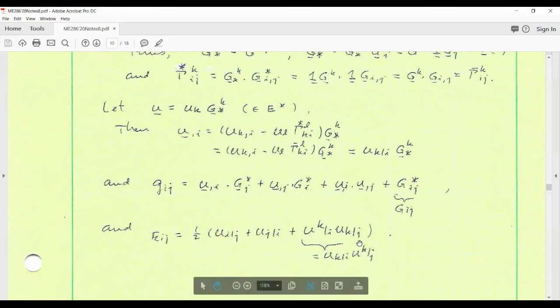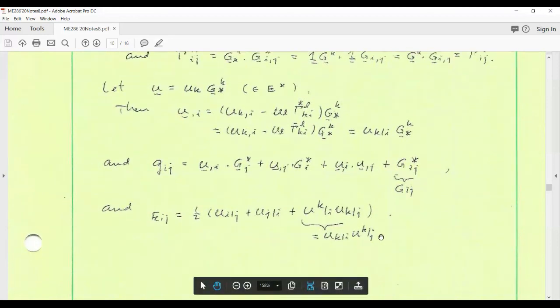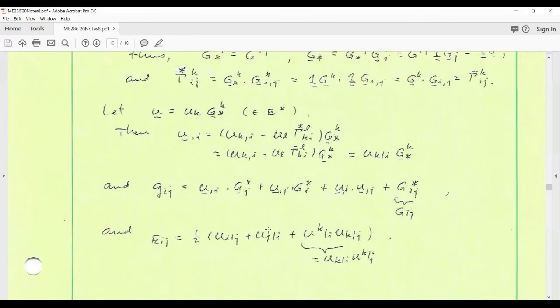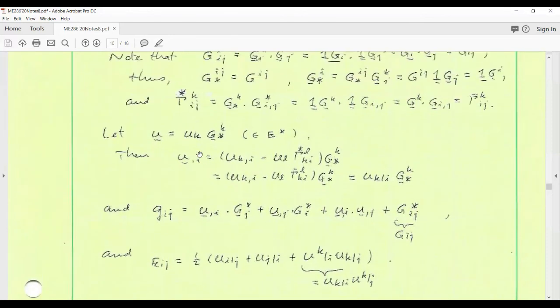You can write this way. So this last expression is what your book that discusses convective coordinates has. This is the correct mathematically meaningful strain displacement relation in convective coordinates, in which you interpret the components as being insensitive to superposed rigid motions. It's just the basis that gets rotated such that Q becomes a spatial vector.